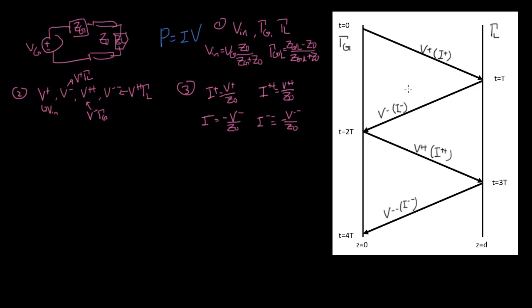The next thing we want to do is we've calculated these changes in voltage or current, which I like to think of as the change in elevation. So we want to start with the actual elevations of each of these triangle slices. I'm telling you how far up or down this goes into or out of the page. At the start, I usually circle this value so that it represents the value of the triangle. V0 is going to be equal to 0 because it hasn't seen the initial incoming wave yet.